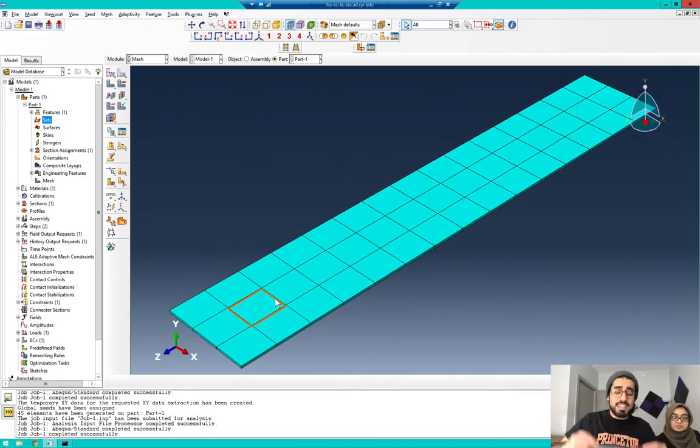Because it's approximating this thing, which is actually a cubic, you know that from the equation, by a straight line. A straight line in terms of bending is stiffer than the quadratic element. So actually I'm expecting results that are stiffer than the quadratic elements.